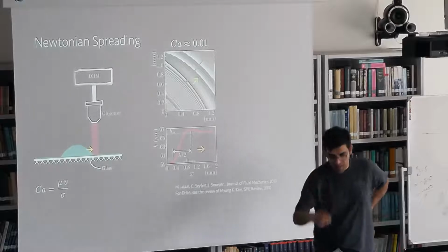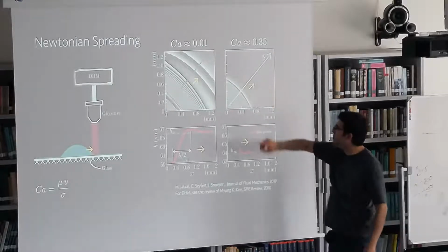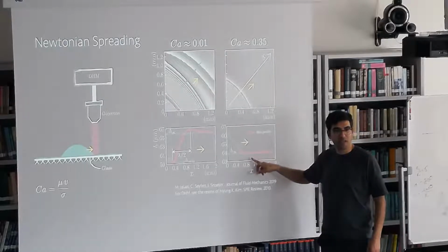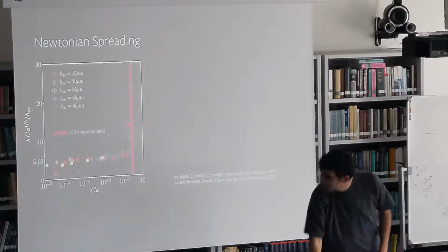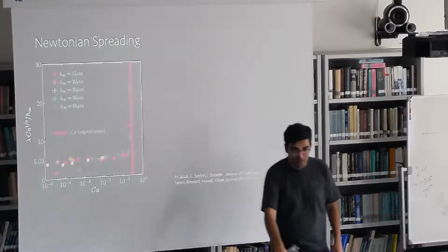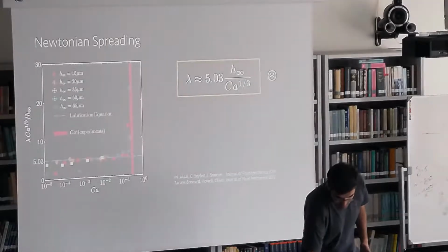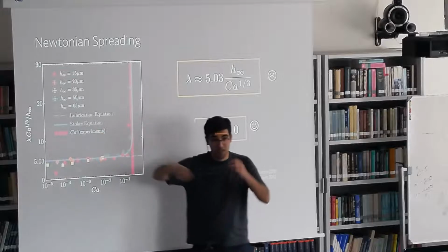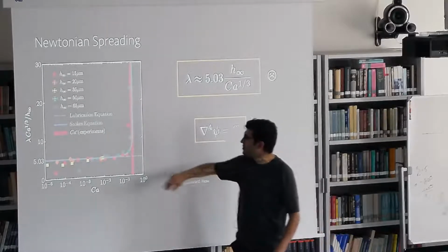Okay, what we found out, now that we're talking about it, is that if your capillary number goes above that critical capillary number, you actually lose undulations. This wasn't clear at all. We thought it was experimental error, but it turned out it's not. Again, since we're talking about it, you can do the theory and get exactly what that number is. That blue line is the theory, which comes from the Stokes equation. The lubrication equation doesn't give you that; you have to do high order solutions to be able to do that.